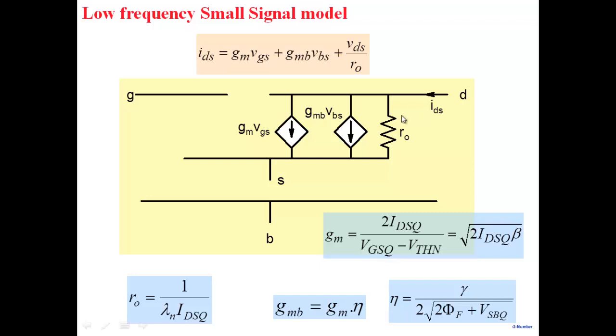Now if you go back and look at the bipolar model, note that this was the collector, and what was the relationship between collector and the base? This was exponential in the base voltage, in which case the small signal model is more problematic. Here it is square. Note that in bipolar, typically the current is exponential with base voltage here. So exponential is a very strong nonlinearity, right? And so when you're trying to linearize it, if you don't want too much inaccuracy, you'll have to keep the input voltage fairly small.